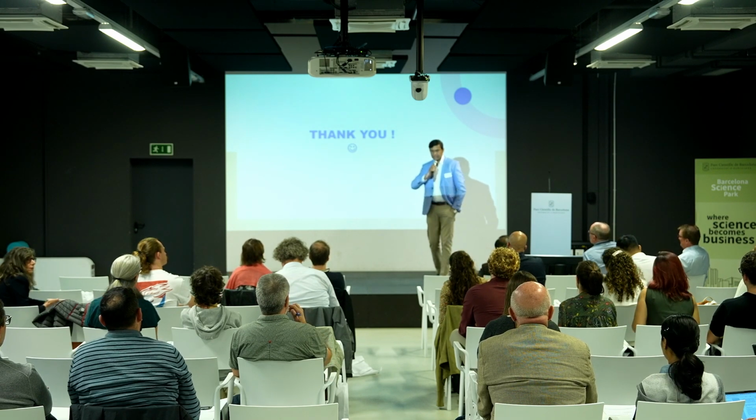That's a good question, actually. When I developed the process, I was working as a solid dispersion expert. I tried this spray drying technology and compared the same product with spray drying and with hot melt extrusion. The first advantage is the solvent, because for spray drying you need to use a solvent, and this HME technology is solvent-free. So of course, you will save the cost.